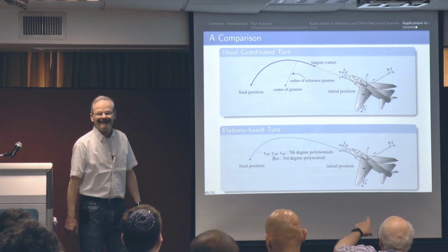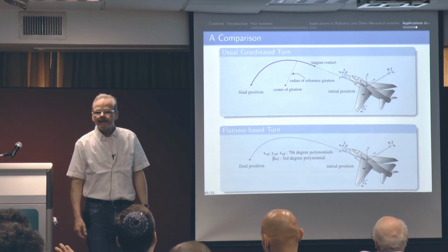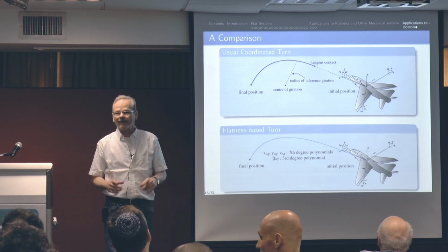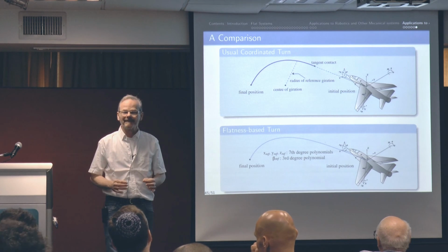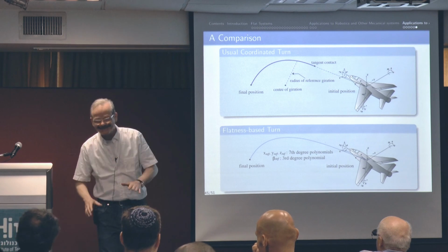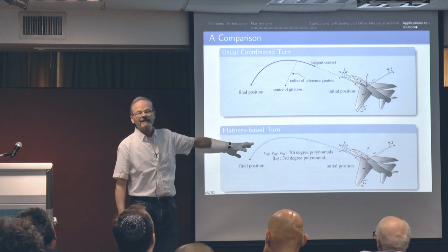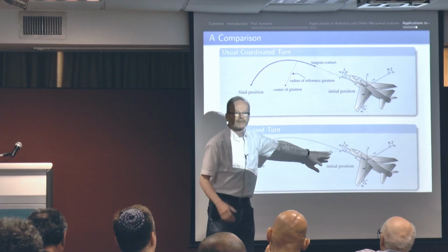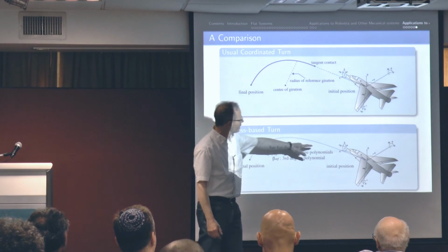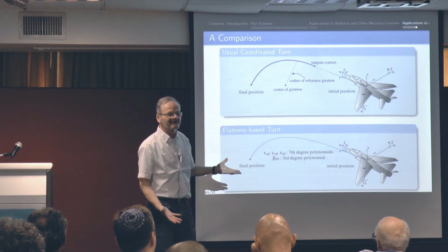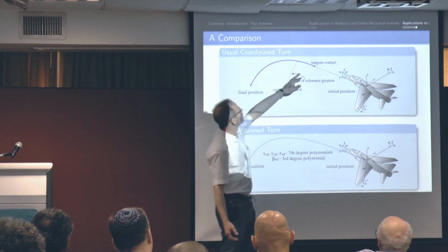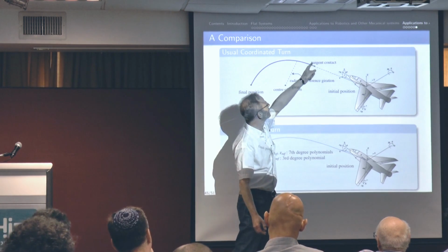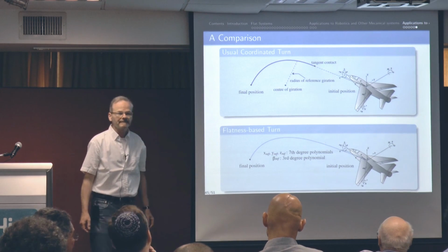And the result, is it a coordinated turn? Is the lateral acceleration on the pilot 0 all the time? No. It can be small, but it's not 0. So it's good for UAVs. It's not so good for manned aircraft. That's right, I fully agree, but it's good for the performance of the aircraft. There's no 0 on this curve, on the second curve? No, it's never exactly 0. It's always small, but this is never a circle. Of course, once this point is passed, the pilot is more comfortable, but the difficulty is to pass this point.